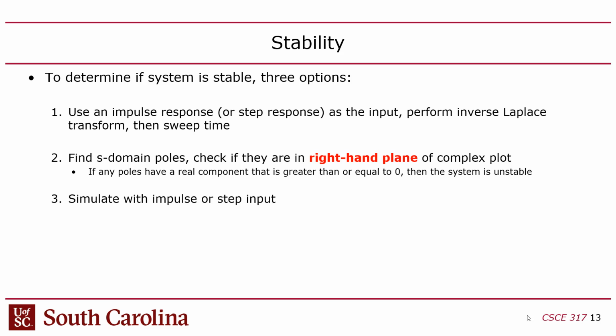Because you can't really simulate something in the, well, you can simulate something in the frequency domain, but then you're just looking at the frequency response, right? You're looking at a filter response, that kind of stuff. But if you actually want to track a signal with respect to time, you have to go to time domain. And that's what Simulink does. It's a numerical integrator. It goes to the time domain, right?